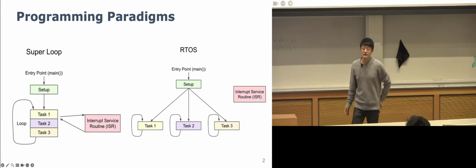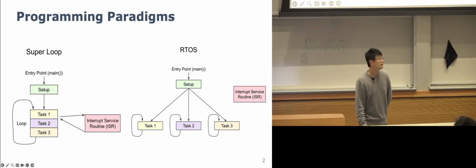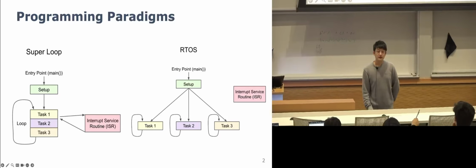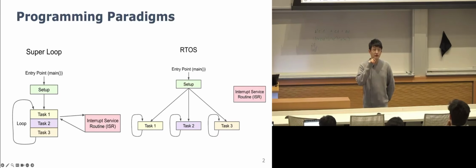I was confused because you said that each task had its own stack pointer address, but they all got loaded into the same stack register. It just saved its own address. I see. So you would pre-allocate memory space and have the tasks use different parts of it, and whichever task is currently running, its stack pointer will go in the PSP.